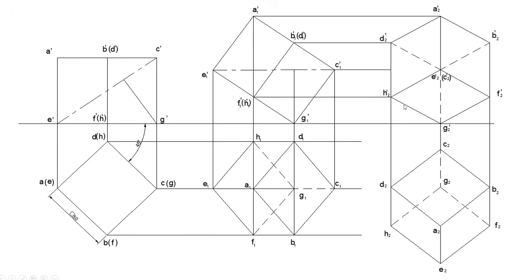Now finally you can get a diagram like this. Since the point E is coming this side, the face EFGH will be coming towards the observer. So in that case the points EFGH will be visible, and the corresponding perpendicular lines also will be visible, and the other face, which is ABCD, will be invisible. In that, the border will be visible. So this is the final condition of the diagram when the body diagonal is perpendicular.